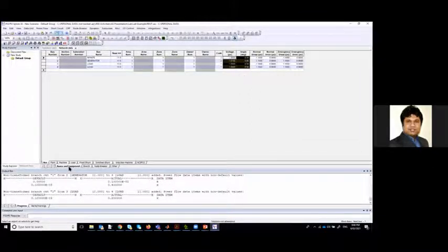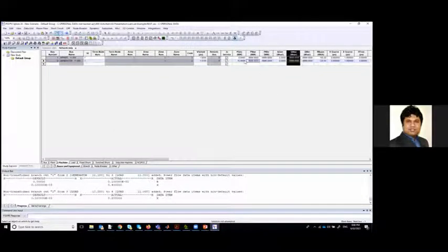Voltage and angle will change, particularly for bus 3 and 4. And for the machine, we only know the P for the generator, but for all the other buses we don't know anything. We don't know Q, and we don't know P for the infinite bus. So after running the load flow, we'll know all the quantities.